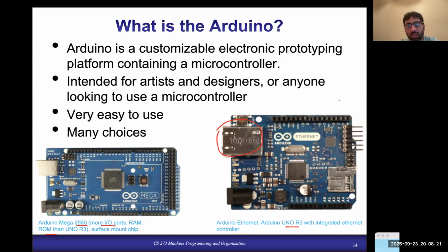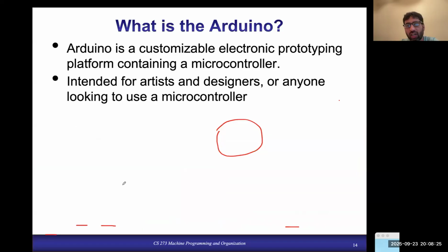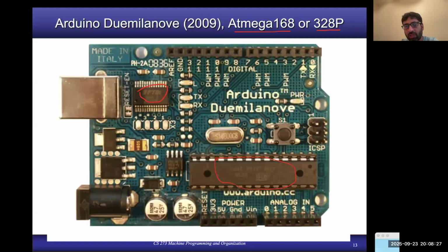Surface mount basically means, if you can see here, that for our purpose there are two different kinds of packaging. This is known as DIP packaging, or dual inline packaging, where you have your chip and there are legs on both sides of the chip. Because of these legs, you can put your chip on the chip holder, which is this thing.